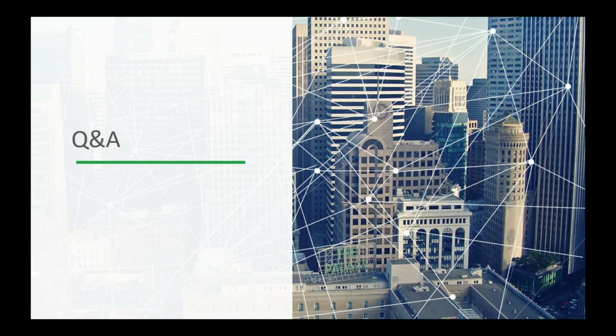Somebody is asking if I'm doing designs utilizing E-band, 70-80 gigahertz. Do I have the information for FCC registration? If you looked at the Excel file, the link summary which I provided, you have all the information in terms of the location, the altitude, the azimuth, the type of the radios and their antennas. It's very easy to go from here to the FCC registration forms.